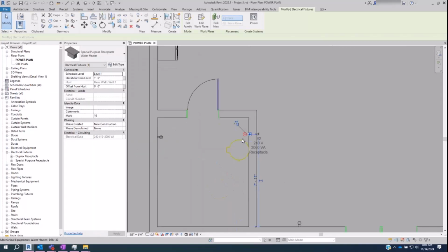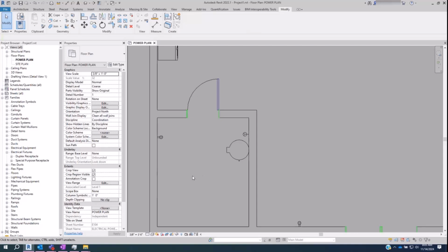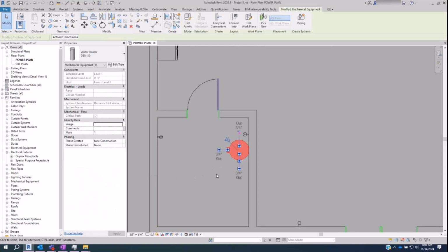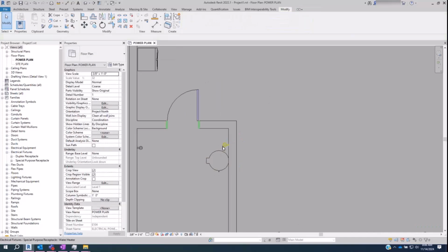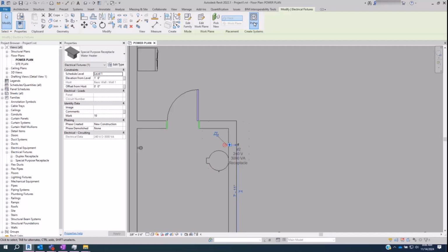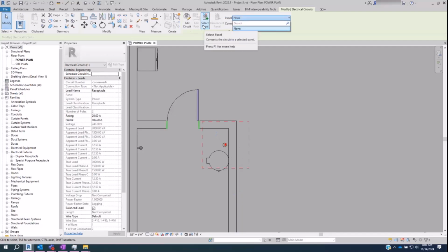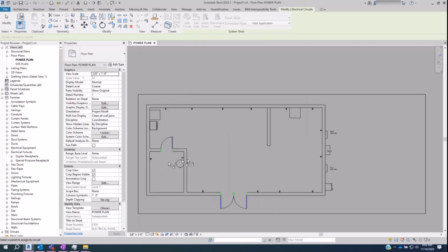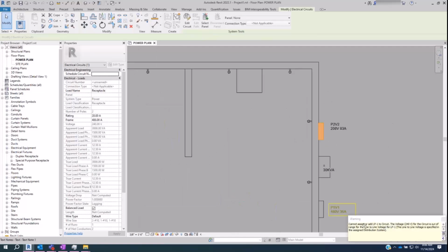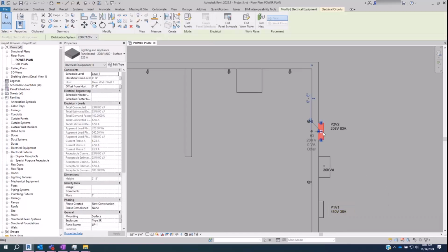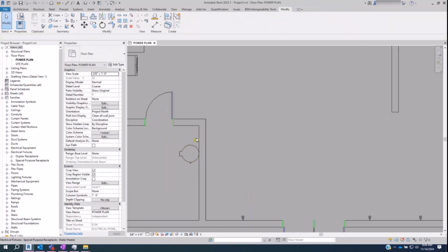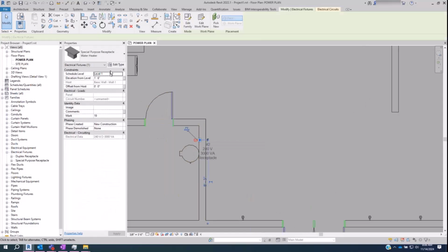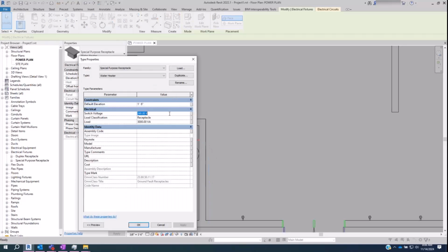And that's that. There are 2 ways we can go about this. We can just leave this as is, because right now it doesn't have a green steering wheel associated with this water heater, and just circuit this, which I will. I'm going to go in power, panel, not sure why that's not showing. Can I assign the voltage? 240 is out of range for line voltage. Did we set that at 208? We did. That's right, because it was 3-phase. Let's change that to 208.